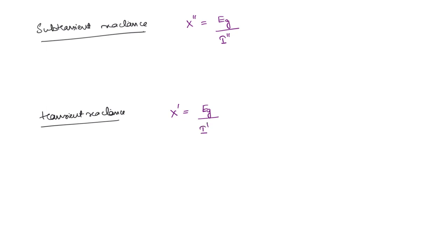Okay. So what is actually happening? The generated voltage is not the same as in the steady state period. It will be higher in subtransient period, but we define the subtransient reactance so that we can use the same internal generated voltage, but we can assume that the reactances are changing over the 3 periods. The reactances are changing. That's what we can consider instead of the internal generated EMFs being changing. Okay.